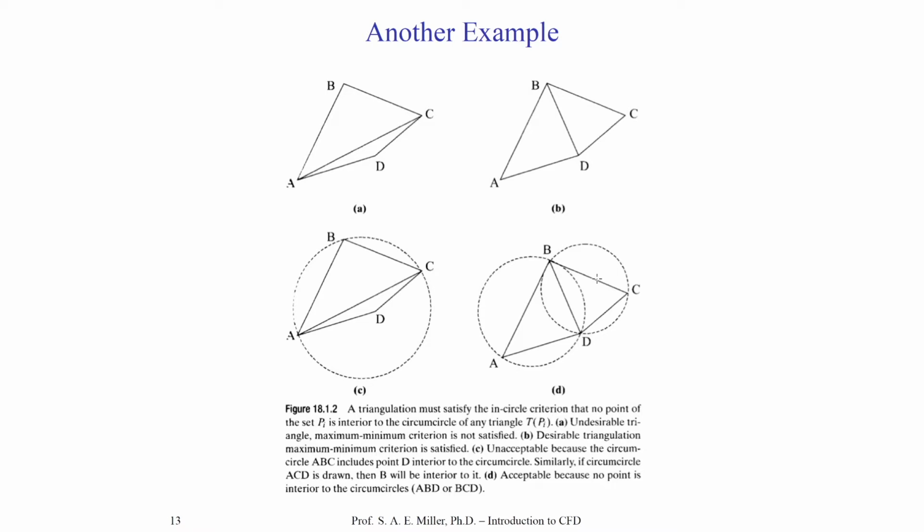How this would happen in practice is we would go through cells and examine them numerically with grid quality metrics and select them as candidates to perform this test. Alternatively, you could perform this test on all elements and find that they all satisfy the criteria of the circumcenter test, and your mesh would be finalized. This is what's happening millions and millions of times a second within your computer when you're creating unstructured grids using these types of techniques.